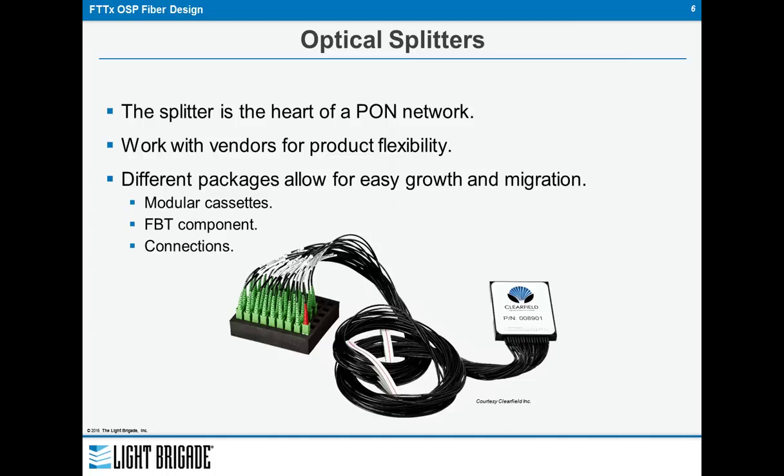One in, multiple out. So you're sharing the power from your transmitter. Economically, this has a huge advantage because you amortize the cost of that electronics over multiple users. They are sharing bandwidth. On the disadvantage side, you're taking a substantial decibel loss. They are splitting the light, dividing it between users, one in, multiple out. So depending upon how many times that is divided will determine the total amount of attenuation.